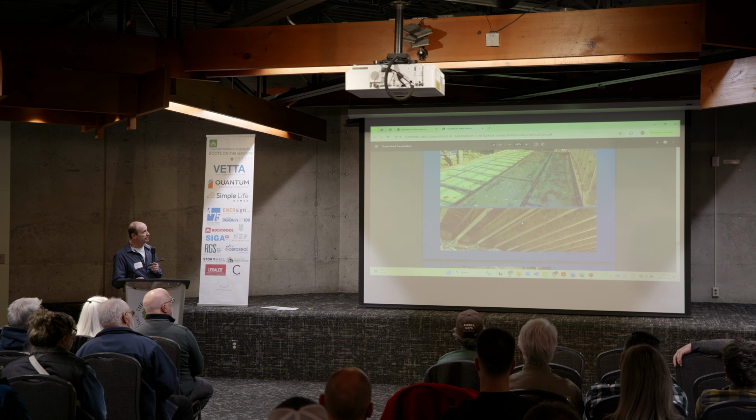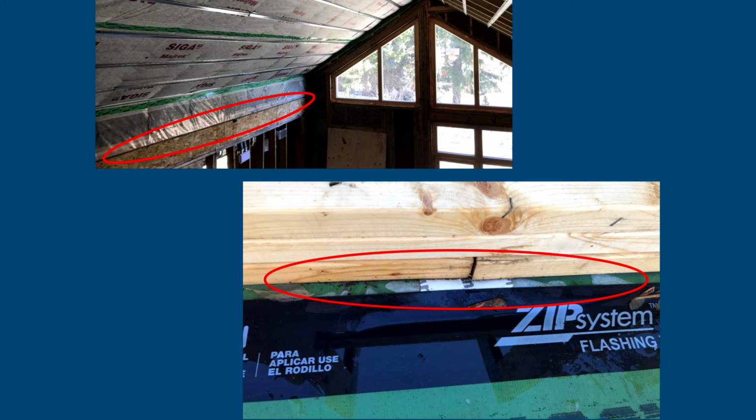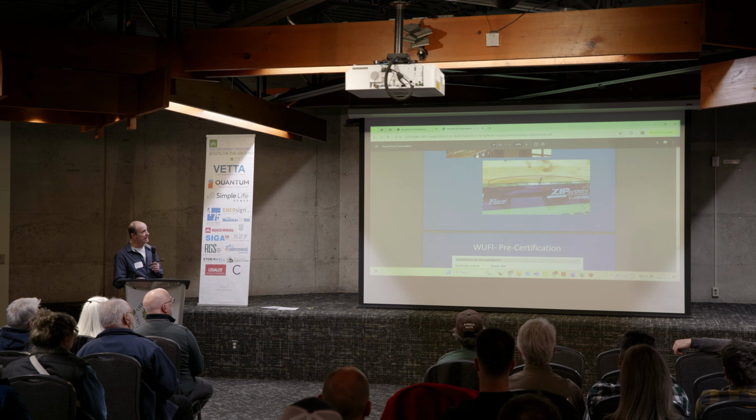which it was. This particular line here where you see the red, that carries through into the inside where it connects to this layer. So now you have the control layer coming through from the outside of the building to the inside of the building. Again, it was planned in advance. Everybody knew what the deal was, and it was executed nicely. That's just a close-up shot showing that particular detail, and it needed to be taped beforehand. Again, the framing guys have to be in the loop and understand that this needs to be sheathed and taped before we continue the framing.